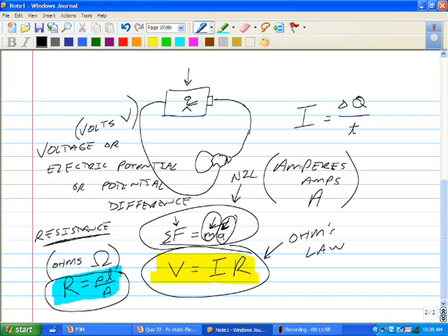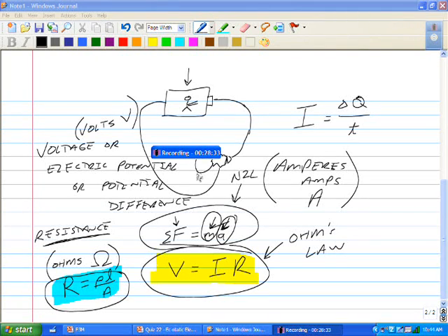Now, instead of putting two 100-foot cables together end to end, you should get a 200-foot cable. Why? What's the 200-foot cord going to be? Thicker. Because if we double the length and double the cross-sectional area, then we can have the same resistance. All right? Okay, we're going to pick up